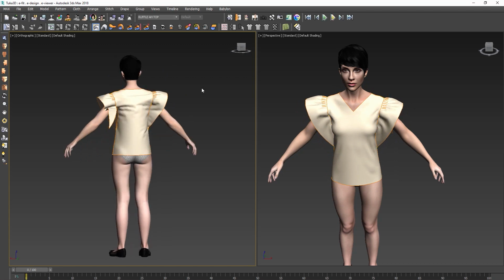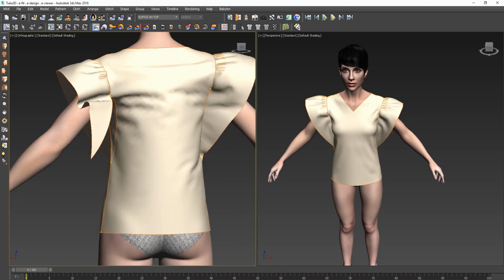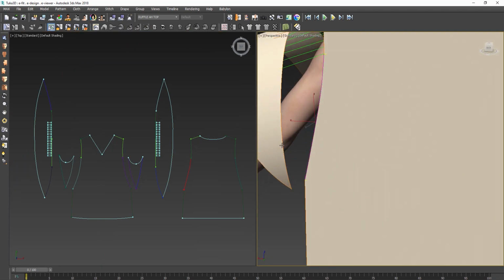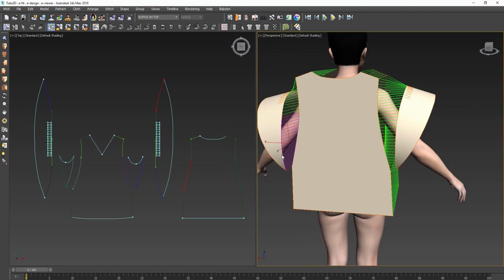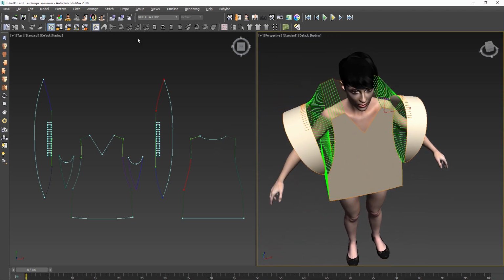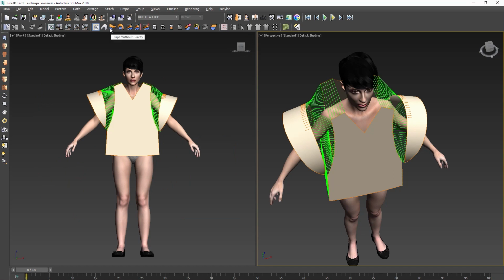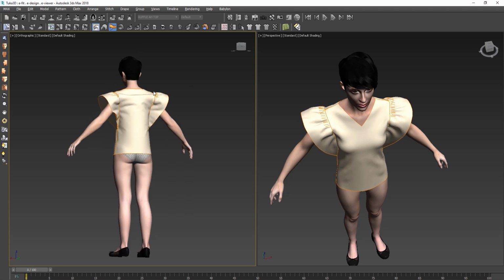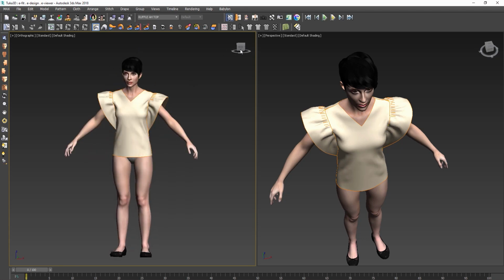Instead of spending so much time checking the stitch lines individually, I would just quickly drape without the gravity, because if your stitch is reversed or you missed a stitch, it will show you right away. You'll be like, oh, I missed one here, so let me go back. Oh, it's here. I don't expect the first time to be perfect. I use it just as a QC check. Later we can use some techniques, like hiding the sleeve first, locking the body, and then draping the pieces separately.